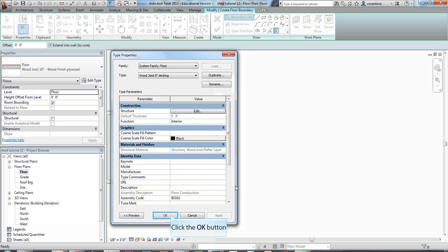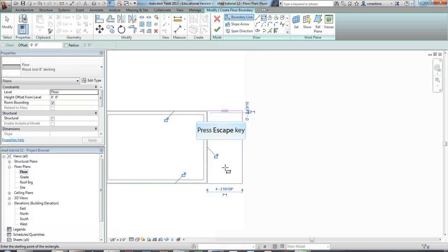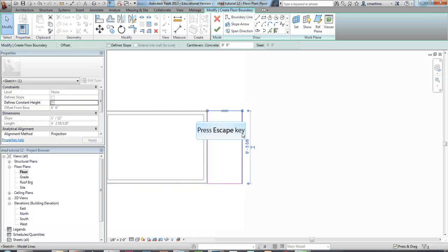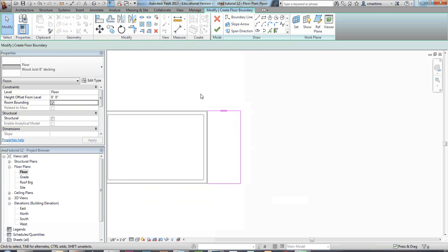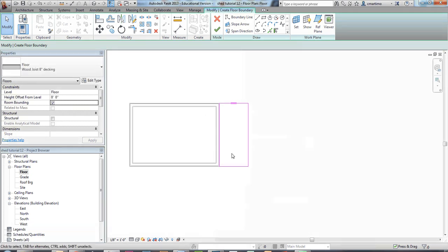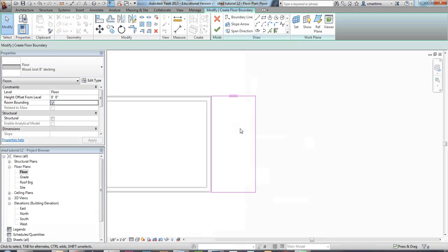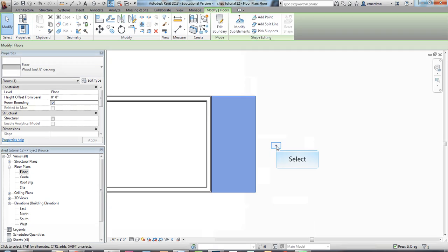And OK again. And then I'm going to establish my little floor that's out here on the outside. So the deck that's coming off of that front there is 4 feet wide, and so I'm just going to select one of my sidelines here and change this to 4 feet, and I've made that the same width as my building, just to kind of keep it simple there with the exterior. And after I have that established as far as its size, then I'm going to hit check. Okay, so then I have my deck off of the front.